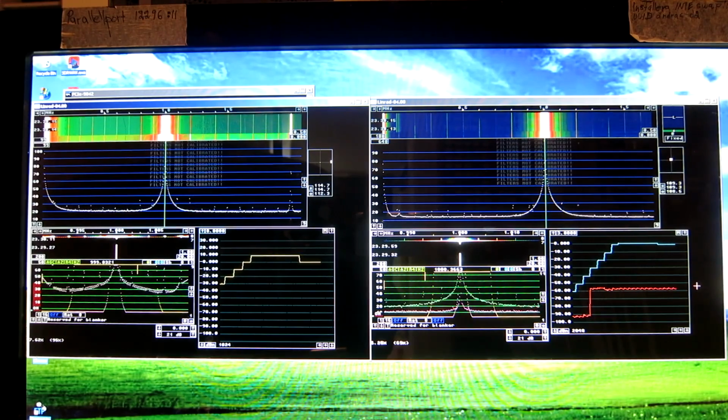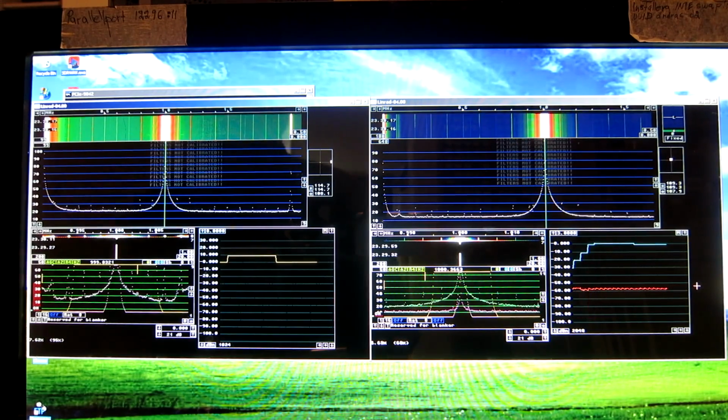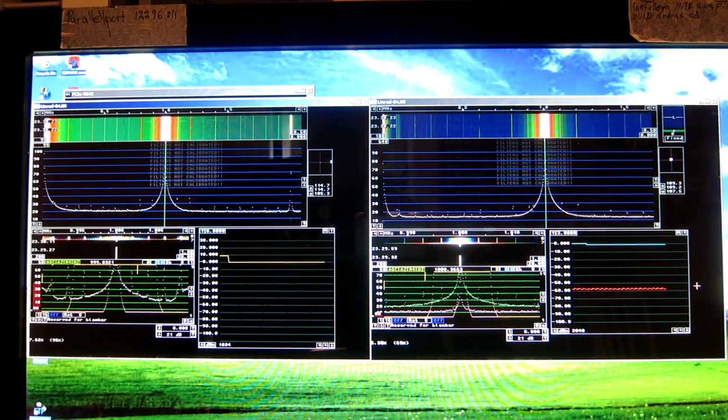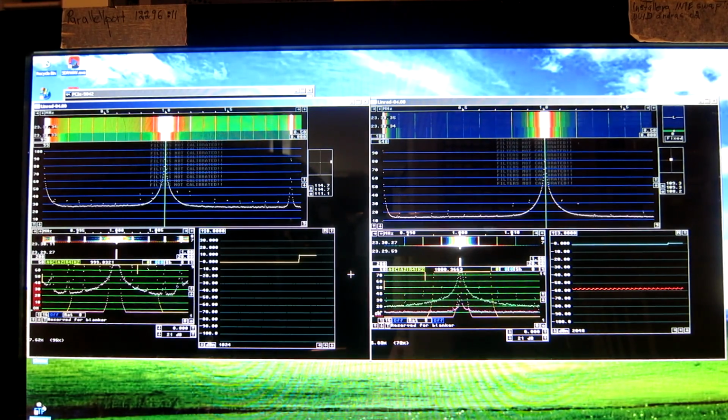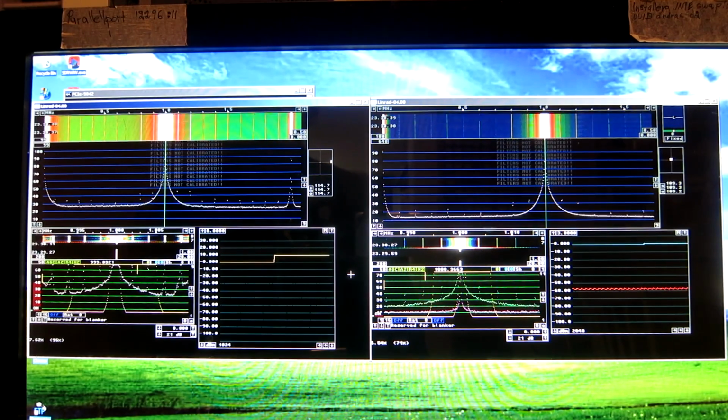This is about 1 dB below saturation and it is 0 on the signal generator and of course it's 0 on the S meter graph as well. I continue to increase the level. Oops, that's not so easy because the generator stops at plus 10. I have to go to 1 dB steps.